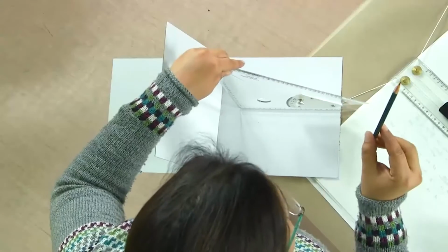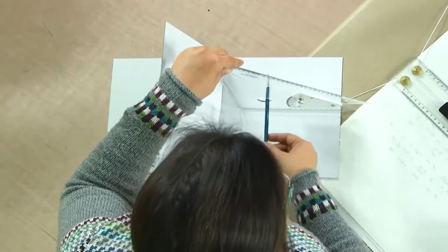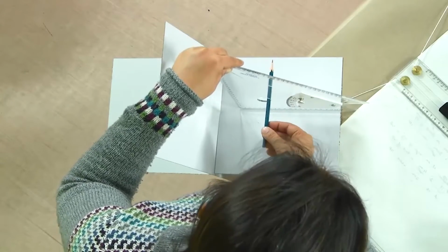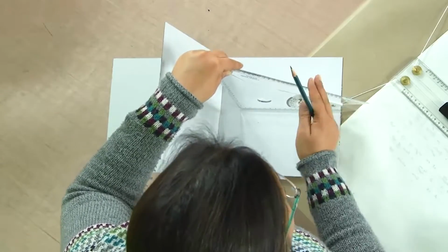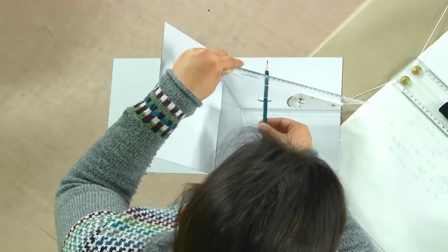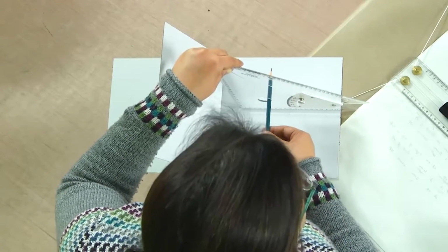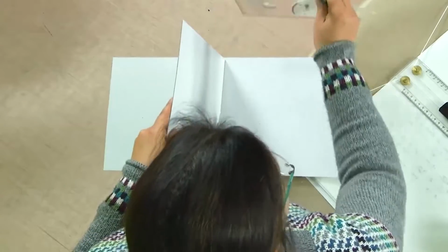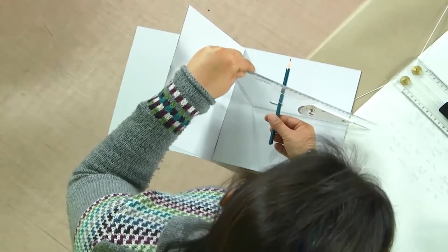Another thing, when we have to classify these different types of plane, is to also see where the axis of the plane lies. So, for example, in this case, if this is the plane for which we have to draw the orthographic projections, a line which is perpendicular to the plane is called its axis. Now, in this case, when the plane is perpendicular to both the reference planes, the axis is parallel to both the planes. When we say that the plane is parallel to a reference plane, it means that the axis of this plane is going to be perpendicular to that reference plane.